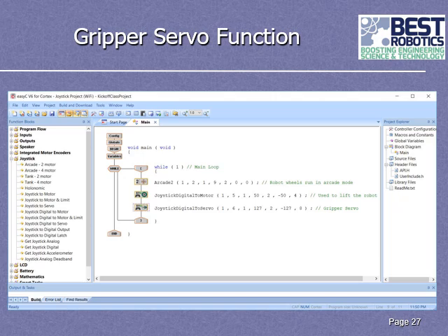So now you have completed all the software you need to run a simple robot. This code will allow you to move the robot around in arcade mode. It will allow you to raise and lower an arm, and it will allow you to open and close a servo. Now, if you decide that in your gripper you want to have 2 servos, or you want to add another motor, you would add either a second servo or a second motor, and you would do it exactly the same way as we did the previous ones. Again, you'd have to pick a port that's open and pick some buttons that haven't been used yet, but it's the exact same process to add more of those in here.